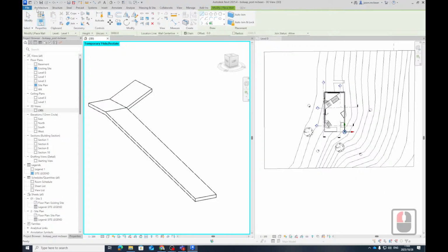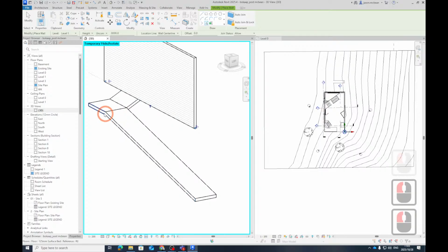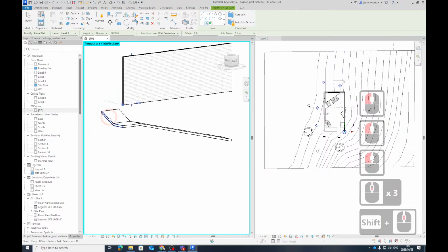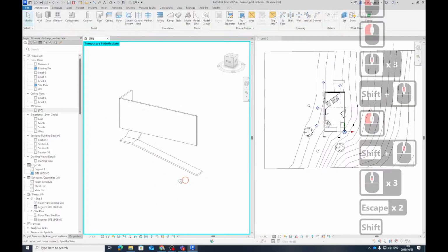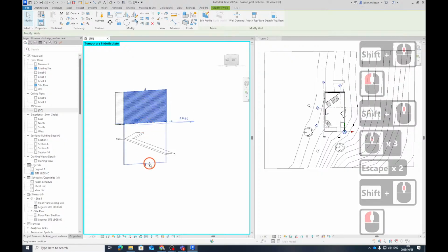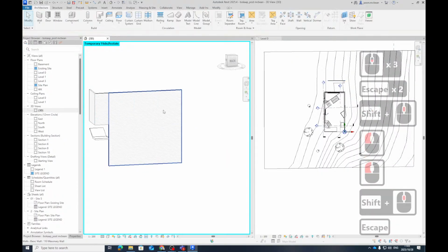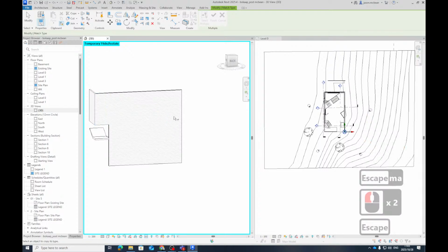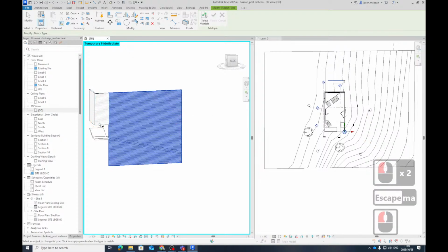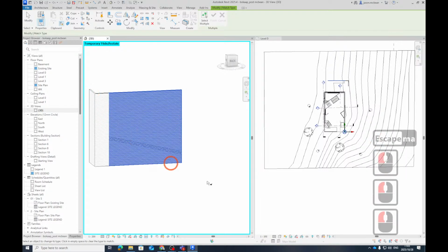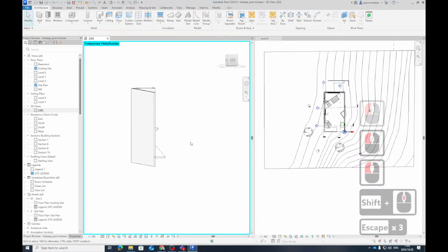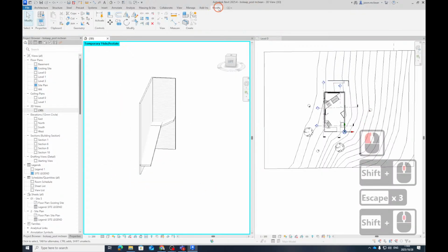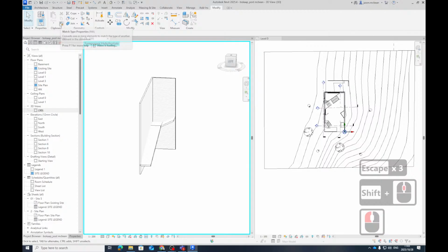So I'm going to say wall. So I'm going to draw a wall. I'm going to say pick line. See what I'm doing? I'm telling it to pick the surface. Okay. I'm going to tell Revit to start the wall below and use match properties, MA, because I wanted this to match this, so it'll extrude everything down. See what it does. Okay, so match properties and modify, MA, it's this thing over here, match properties.